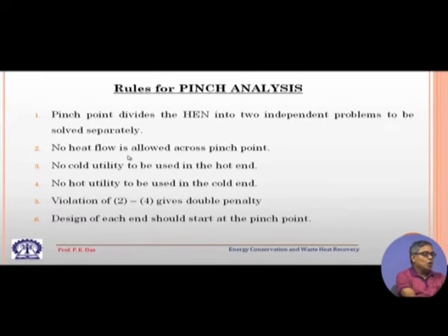Second thing we get, no heat flow is allowed across the pinch point. The pinch point means at the top there are sub networks, but from the top sub network to the bottom sub network there is no heat transfer across the pinch point. Then no cold utility is to be used in the hot end, this is very important, and no hot utility is to be used in the cold end, this is also very important. Violation of rules 2 to 4 gives a double penalty.